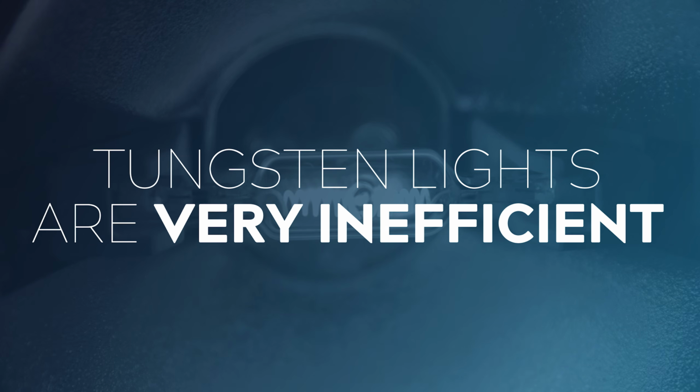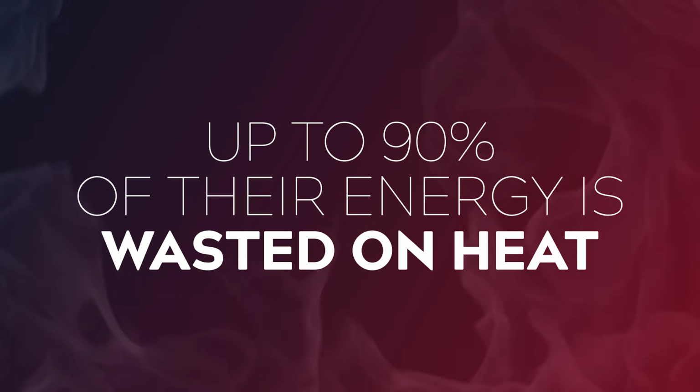So what's the downside? Tungsten globes are very inefficient, especially when compared to some of the more modern light fixtures out there. This inefficiency results in really large power draws, and up to 80 to 90% of that energy is being wasted on heat. As a result, these globes get very, very hot. The bulbs themselves often reach temperatures in excess of 500 degrees Celsius.